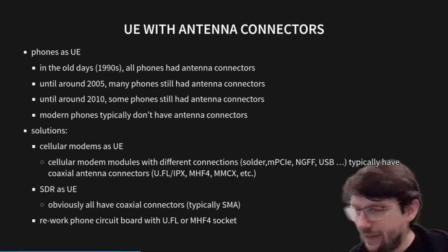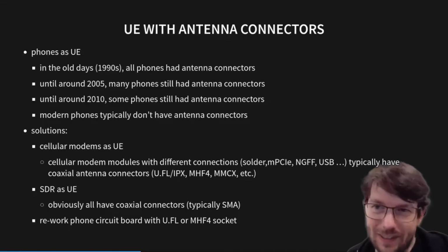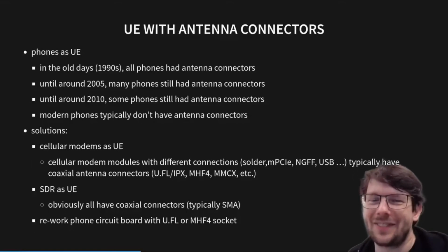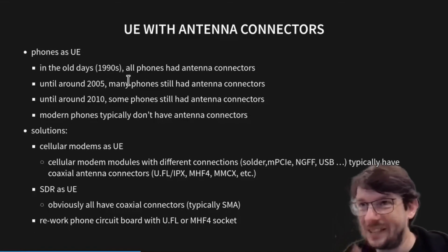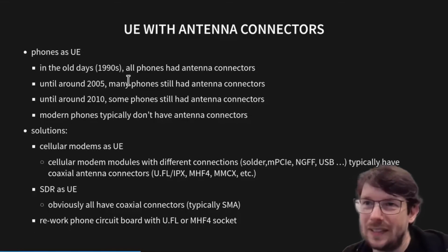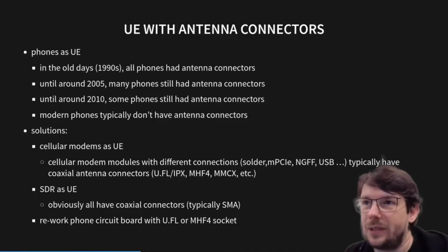If we use phones, I mean, in the initial example, it was an SDR, where, for example, with srsUE, since we have some SRS people here, then of course it's easy because we have separate connections. But in the old days, if you look at phones from the 1990s or even until 2005 or sometimes until 2010, you could find phones that had antenna connectors. Those days are gone. So basically, you can't use unmodified modern smartphones in such a wired setup if you really want to have a wired setup.